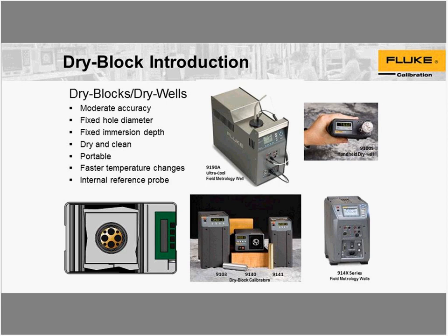Typically, though, in a dry well, depending upon your unit, your immersion depth is going to be fixed depending upon the design. Very portable. One of the other things that people tend to lean towards for a dry well is they're fairly rapid to go up and down in temperature, and that they do have an internal reference probe that does control the display accuracy, so you can get fairly decent display accuracy when you're calibrating, say, thermocouples or gauges that don't require a whole lot of precision.